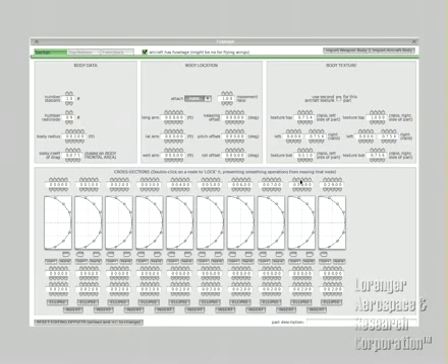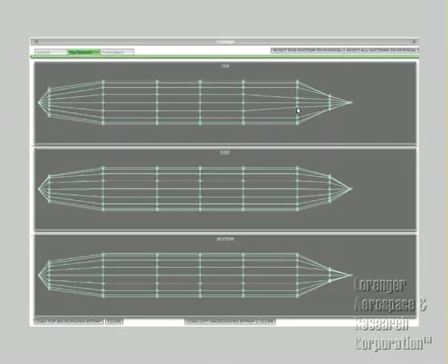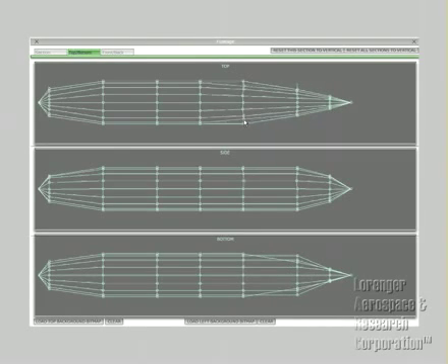Knots, what have you. Next up, I always like to quickly adjust the fuselage to get a general length and rough shape. What this means is you go to these sections here and just trim them out manually, making rough estimates of where you think things will be. You can copy and paste them like so, just to get the job done quicker. They added that in version 8 of PlaneMaker, I believe. And just quickly slam it together.